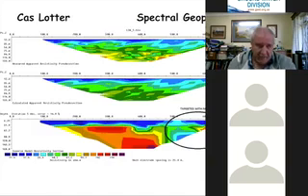Then the next example over there was a dipole resistivity tomography survey. What had happened over there is that there were 8 dipoles, if I remember correctly, with an electrode spacing of 25 meters. All right. So then you're having a dipole from 1 through to 6, and you're doing an inversion of the data, and that's your raw data, that's your inverted data. And if you go and target it there, there's a structure there at 480 odd meters, right? Very clearly sitting over there.